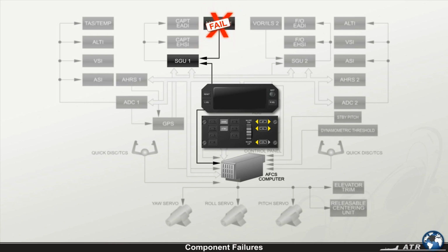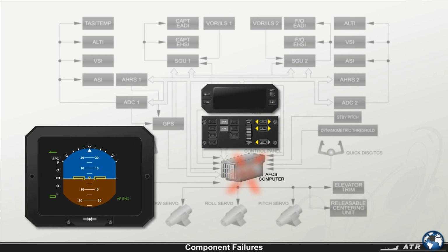In case of an ILS failure, when not in dual coupled phase, the autopilot remains engaged on the coupled side. And in case of an ILS failure in the dual coupled phase, the autopilot will perform an automatic selection. In case of a failure within the AFCS, an autopilot message will be displayed on the EADI and an explanation message will be displayed on the ADU.